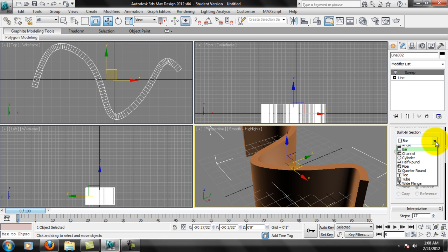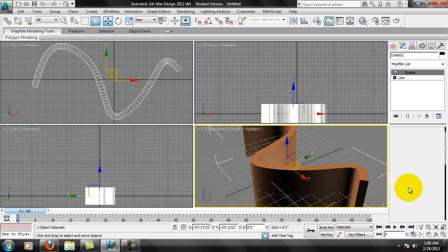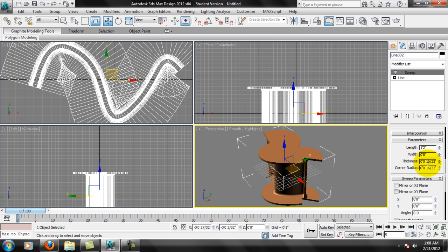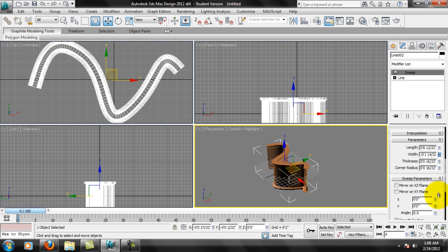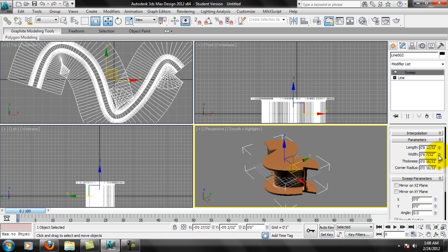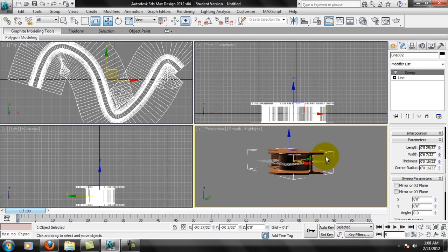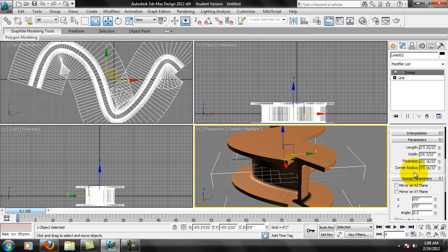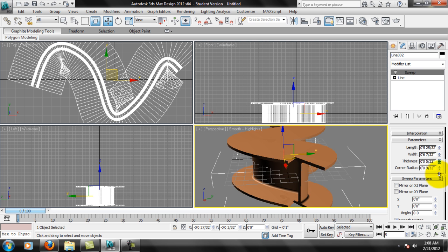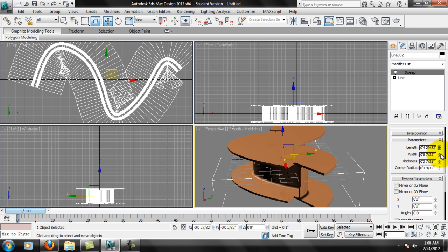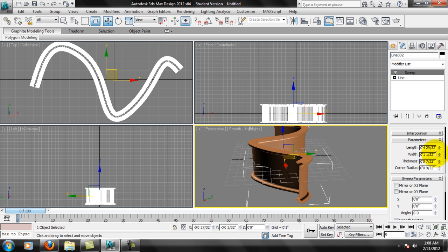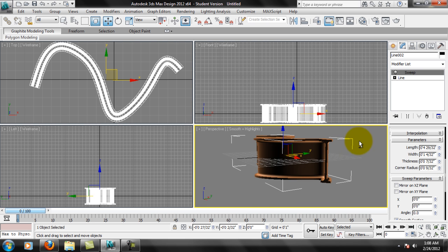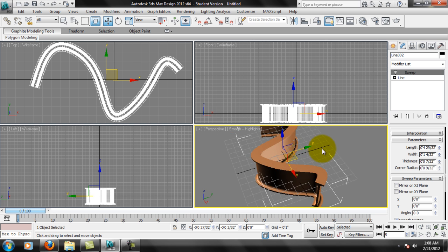Okay, so some of the other basic shapes that you have in here, these are just the basics. Make this smaller. Not that small. So this is an H-beam here, an I-beam or whatever. A little big still. There we go, right. Oh, too much. Right there. So there's your sweep of that I-beam on that path. So sweeps are really handy.